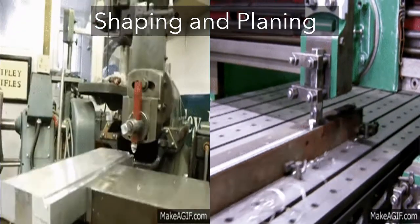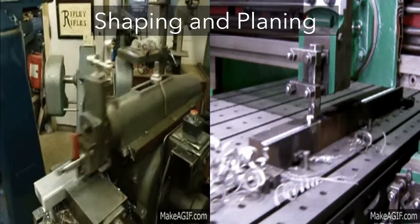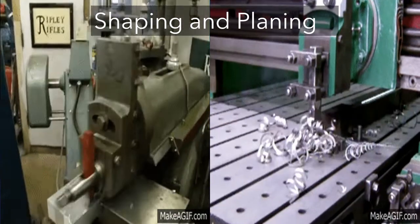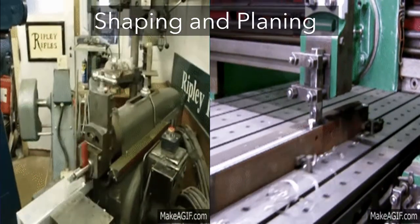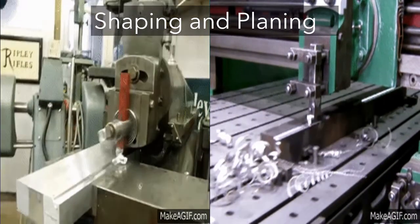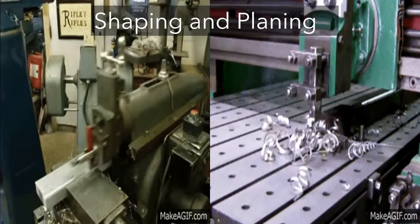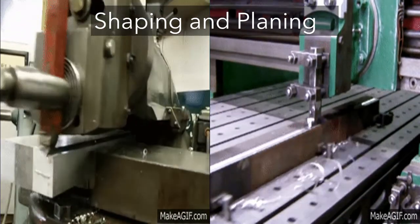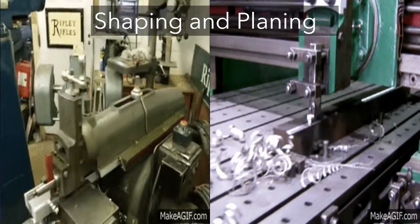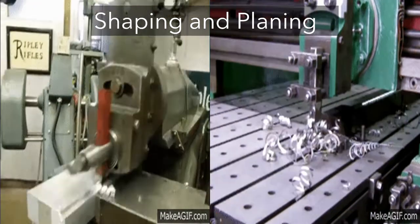Shaping and planing are similar operations, both involving the use of a single point cutting tool moved linearly relative to the work part. In conventional shaping and planing, a straight, flat surface is created by this action. The difference between the two operations is that in shaping, the speed motion is accomplished by the moving of the cutting tool, while in planing, the speed motion is accomplished by the moving of the work part.